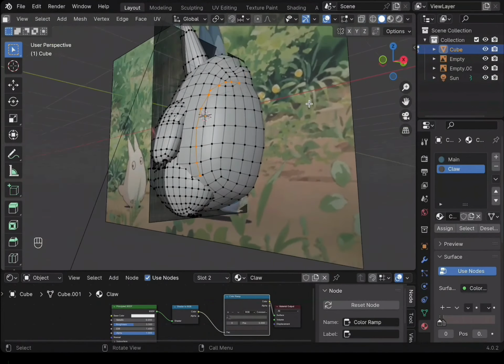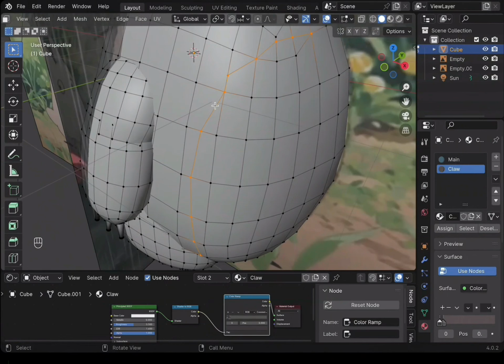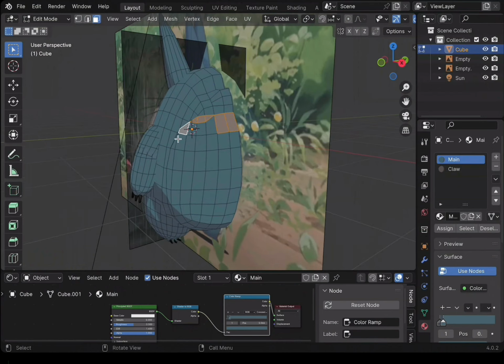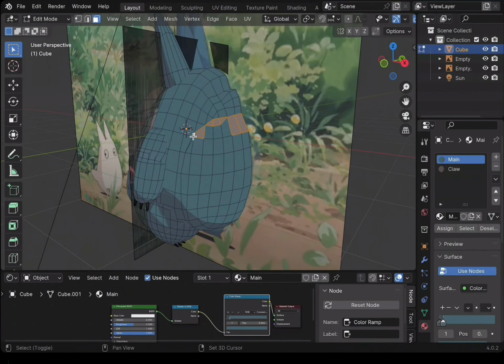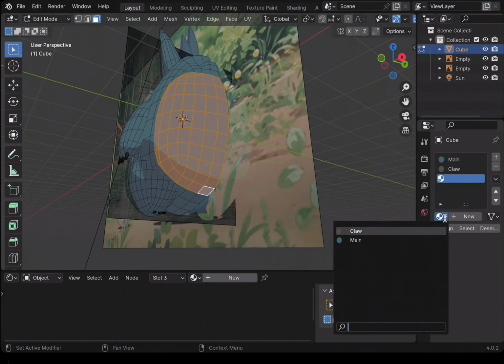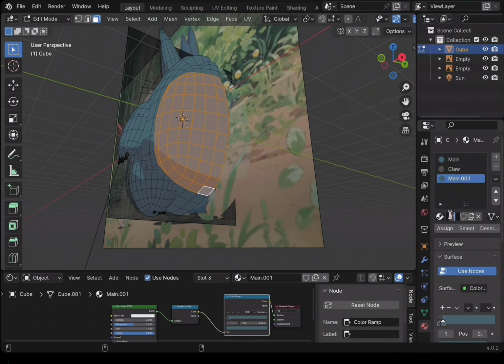It took me several tries and some adjusting to get it to look right. After that, change the viewport to see the color. Now select everything within the section you traced, and go to Materials. Again, add a new material by copying the ones already made and changing the color to white.